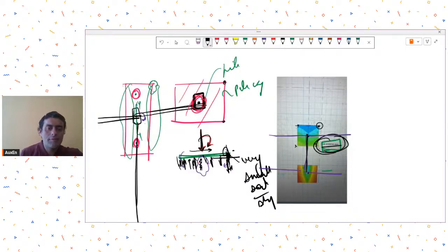Additionally, you may assign translational restraints at the corners, just the corners, if required, because anyway your pile cap system is not going to slide as such. So you may consider assigning corner springs, translational restraints, and additionally consider adding tie beams at plinth level or ground level. Even after that, if you are getting settlements, it's okay to ignore after finding out properly the reason for this type of settlement. Okay, all right.